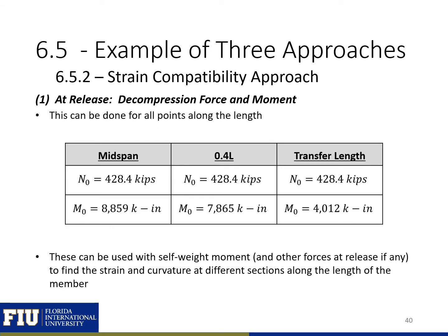The values on the previous slide were for our decompression force and moment at midspan, but we also need to find our decompression force and moment at 40% length and at transfer length, the three locations where we'll be calculating our stresses.